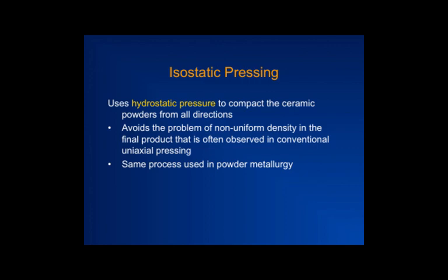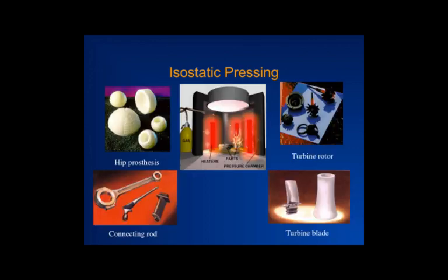Now, if you're making a few components that require very high strength or hardness or high temperature resistance, all affected by density, then you can go to something like that. But as the volume of manufacturing increases, the ability to use this type of approach goes down. You can alternatively fill the powder in a deformable material such as a tin box, or you can even make it into a very thin walled steel container, depending upon the temperature you're heating it to.